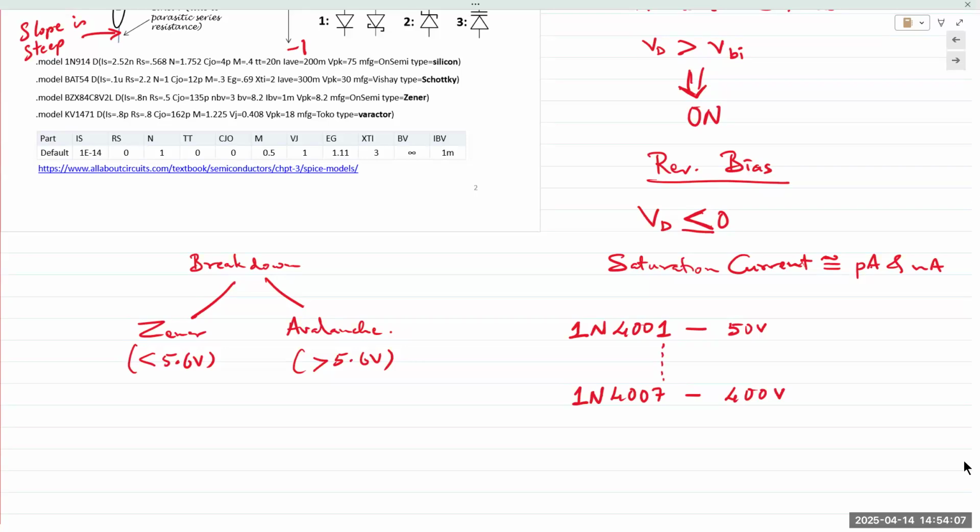But at the same time, the electric field is increasing, and now you're supplying more energy to the electrons in the semiconductor material. At a certain point, the electrons acquire enough energy that the electric field will rip the electrons out of the lattice structure and create free electrons.